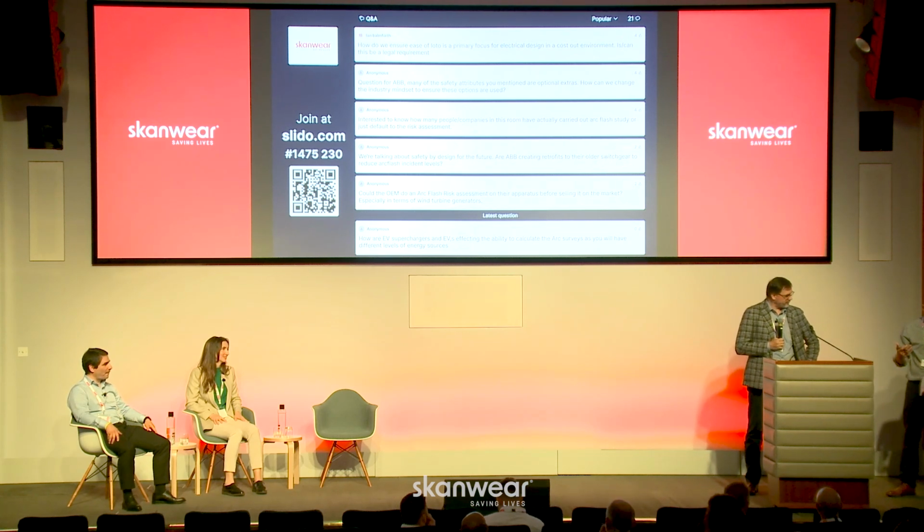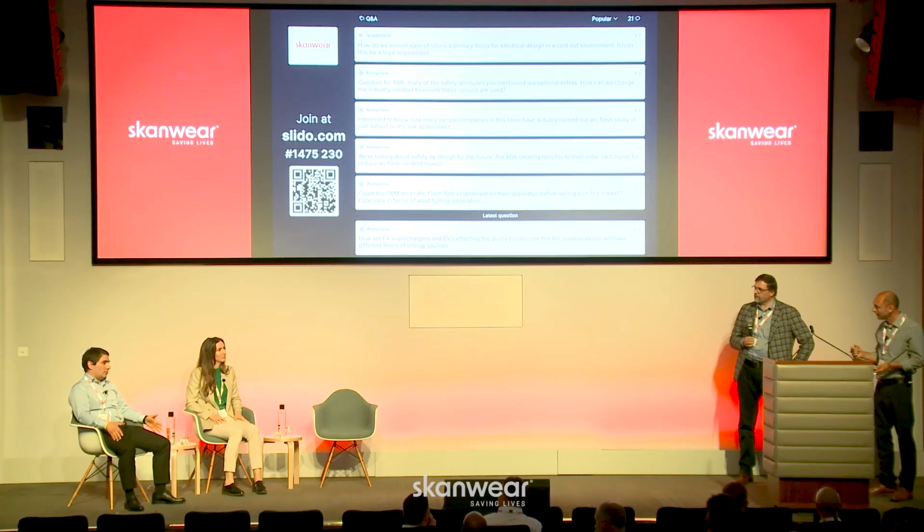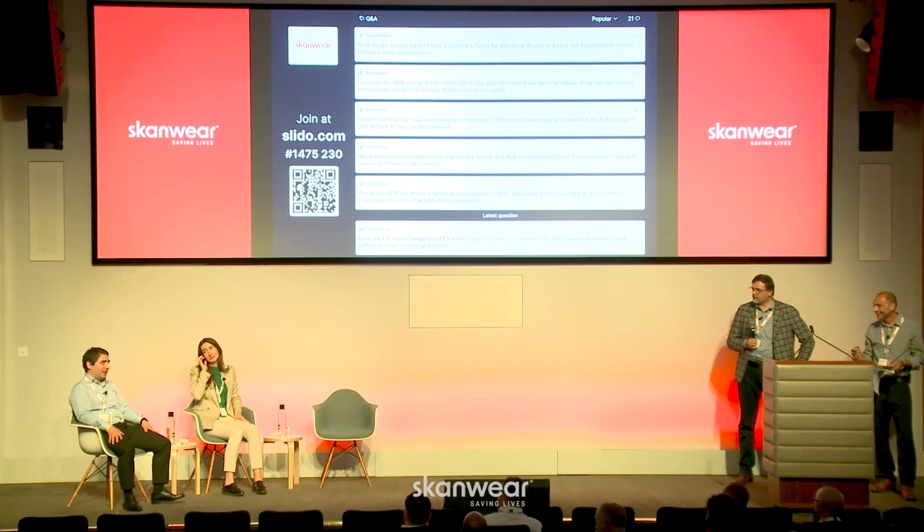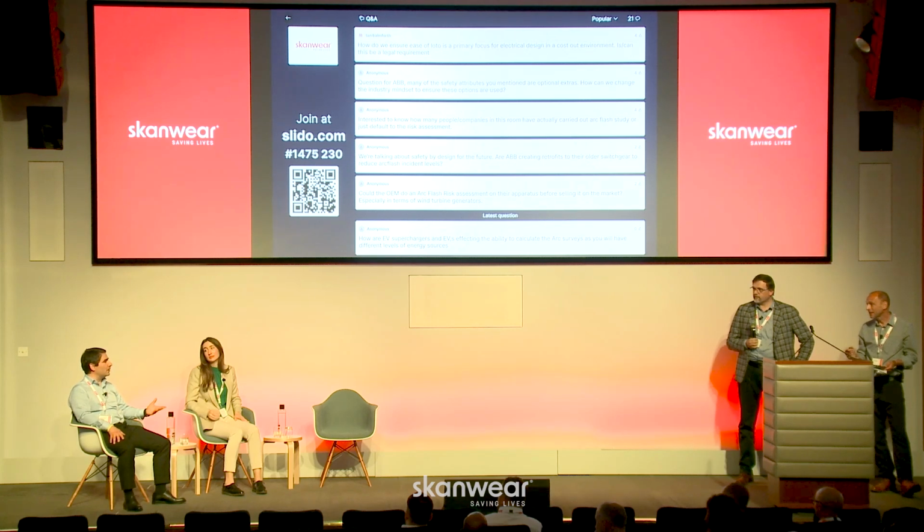Okay, another one then. Sertac, I think this was one more for you. Could the OEM do an arc flash risk assessment on their equipment before it's put on the market? Well, they can, absolutely. There are obviously test laboratories; they can take the switchgear to accredited laboratories and get it tested and approved. Then they can fit their switchgear with the manufacturer's arc flash protection gadgets as well.